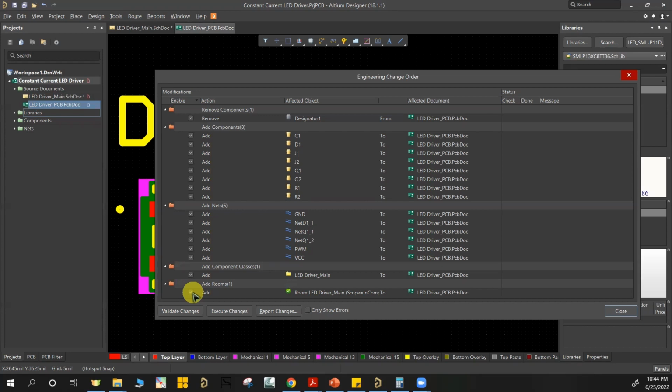So room kind of helps you place different schematic sheets all together. Imagine that you have 50 parts and 5 schematic sheets. You want to be able to separate them by each schematic, and the way it does it is just using room. All the parts in one schematic sheet will show up under one room.